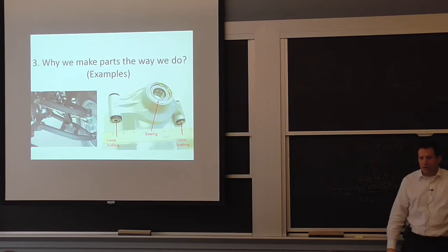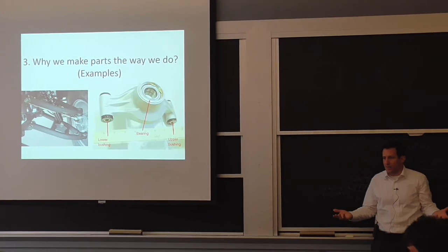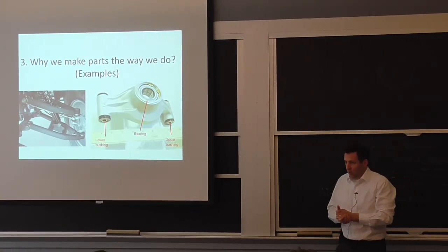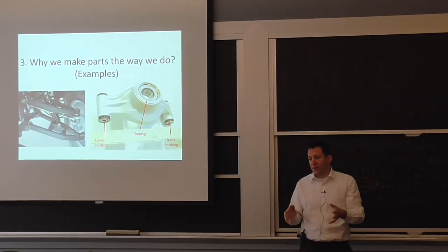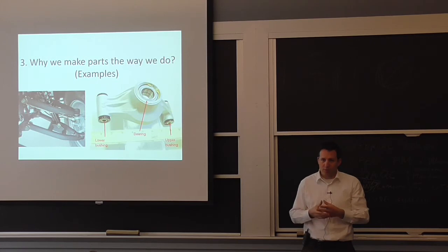Welding, if you're going to do it in series, is very, very cheap. And wrought material is also very easy and easy to control. What it means, with all these welds in there, is it's just this kind of mild steel that we were looking at with the deformable microstructure, and you wouldn't want to be doing this with a high strength steel. You just can't.